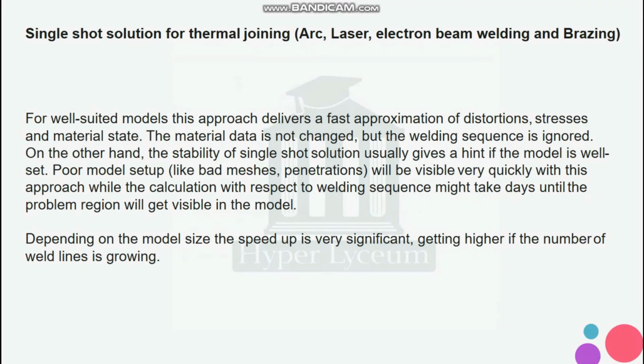Poor model setup like bad mesh or penetrations will be visible very quickly with this approach, while the calculation with respect to welding sequence might take days until the problem region will get visible in the model.